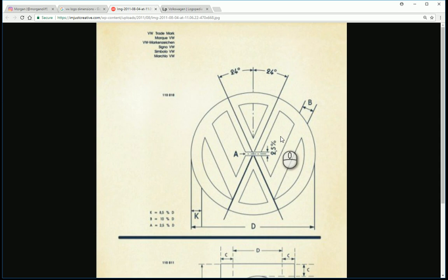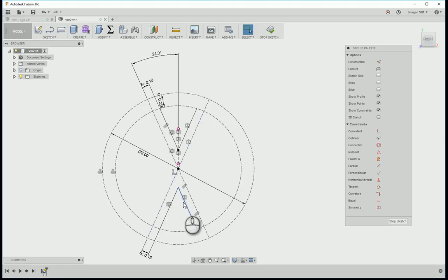Okay, so this is as it sits. That, and then this is an easy one because it terminates at the center line, which we've already drawn, and it's going to be parallel to this. So that's a nice next line to establish. So we'll pop it up here, somewhere kind of random, alpha line, wherever, just so that it's not snapping to a point or an angle that we don't want. And then we'll say that this is parallel to this, and that this line is parallel to this line. And that's fully established here.